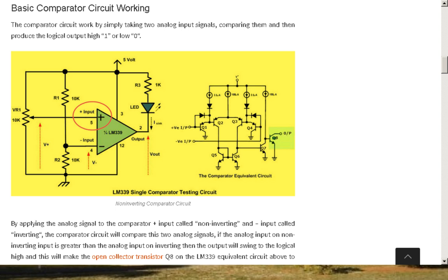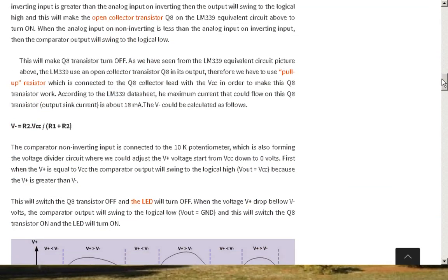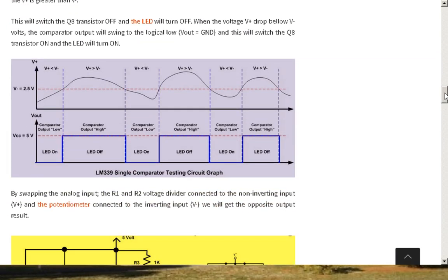But we're going to try to use it to separate noise, and how that's done is two signals are put in. One signal is the reference, which is just the noise, and then the other signal is the signal plus the same noise that you're putting in down here. And so what you're doing is you're comparing the two, and supposedly all that's left on the output is just the signal. Supposedly. I haven't actually done this electronically, and at some point this is where we're going with all of this.